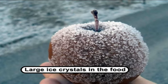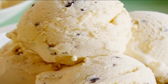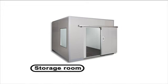The resulting low rates of freezing cause the growth of large ice crystals in the food and allow plenty of time for the flavors of different foods to mix. This hurts the quality of the product, and thus this simple method of freezing is usually avoided. The next step is to use some large fans in the cold storage rooms to increase the convection heat transfer coefficient and thus the rate of freezing.